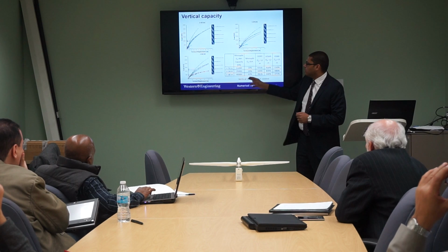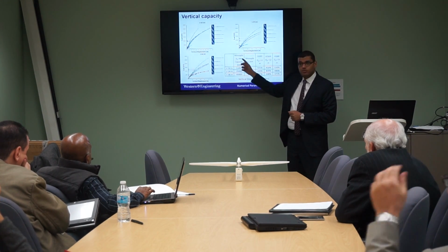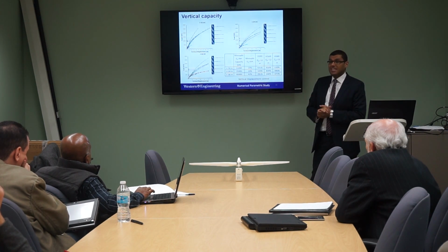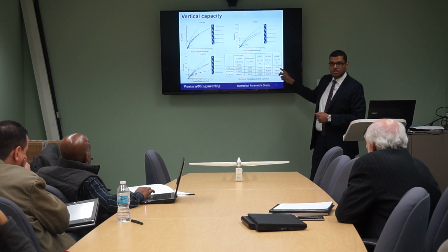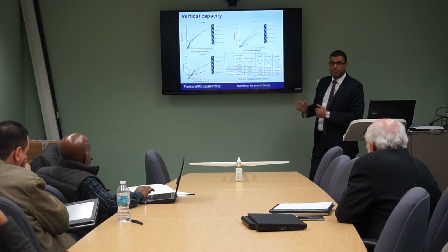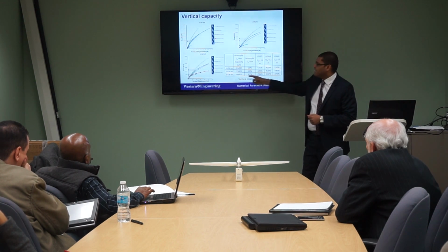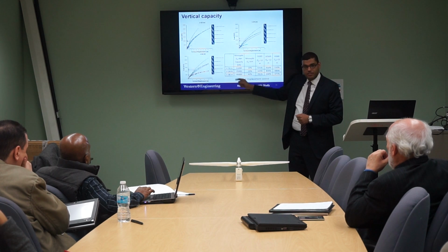So for the monopile with diameter 6 meter compared to the monopile with diameter 4 meter, we can see a 20 to 42% increase in capacity. While adding the plate, we can see a 500% increase in capacity due to the effect of the plate. And we can see here that this effect is reduced with the increase of pile length due to the effect of the pile friction.